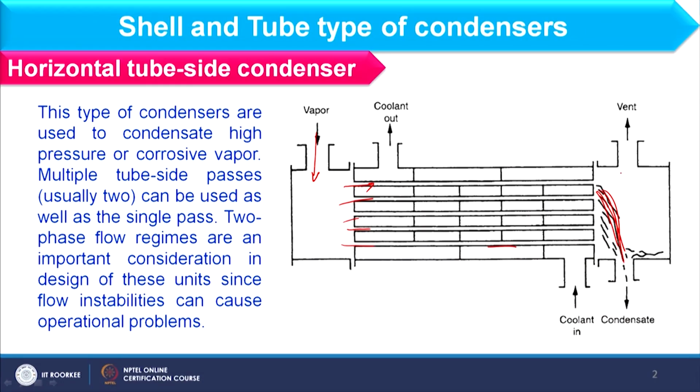But where condensation is occurring in the tube side, the shell side structure will be the same as in a normal shell and tube heat exchanger, so here we have a horizontal cut in the baffles. Further, when vapor is entering the tube side, we have the vent on the tube side, but at the opposite side of the tubes.